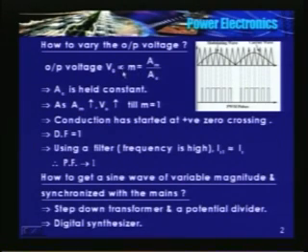So there exists a relationship between the output voltage and the magnitude of the sinusoid. V naught is proportional to m, where m is the modulation index. It is equal to the magnitude of the sinusoid divided by the magnitude of the carrier. Since the carrier magnitude is held constant, V naught is proportional to m, or V naught is a function of the modulating wave. So S1 starts conducting near the zero crossing of the modulating wave. Therefore, displacement factor is approximately 1.